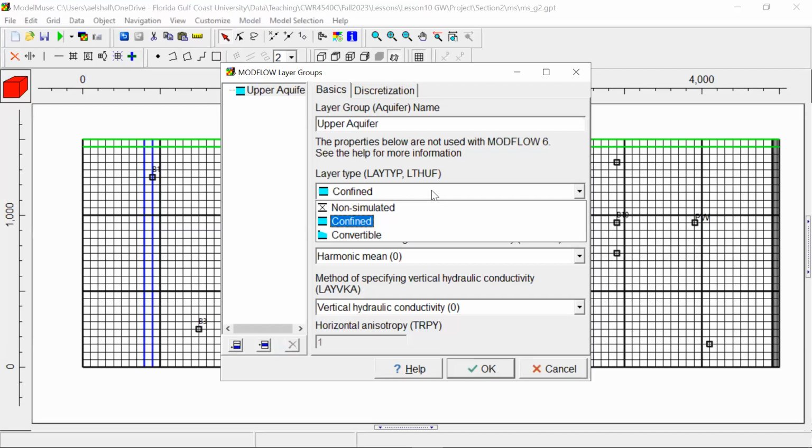But that's okay. The reason that I wrote this equation is because that's exactly what MODFLOW does. If you selected here, MODFLOW will not solve for unconfined aquifer directly, because that's very difficult. If you selected the convertible one, MODFLOW will solve this equation for the unconfined aquifer.